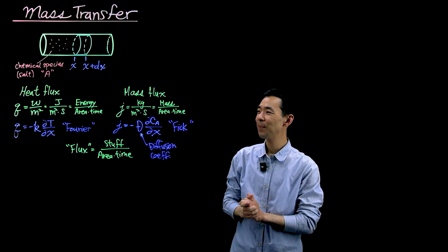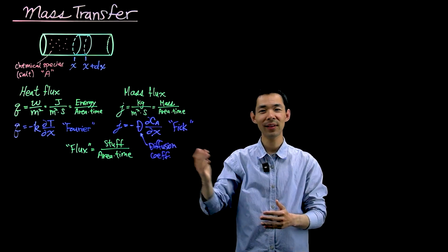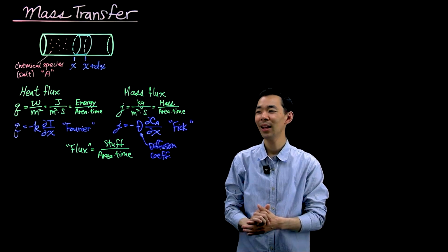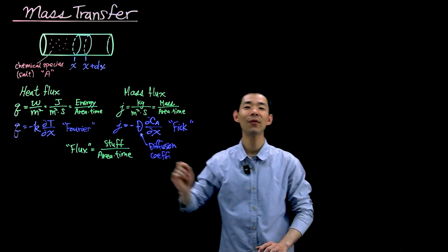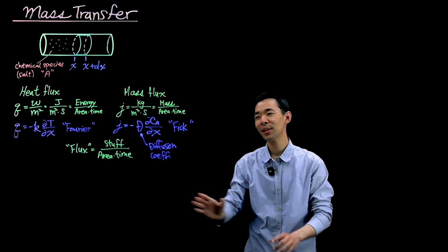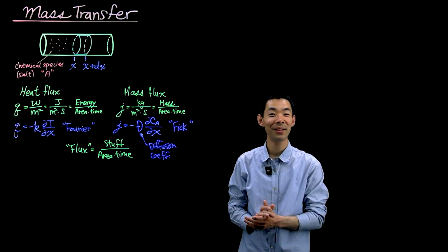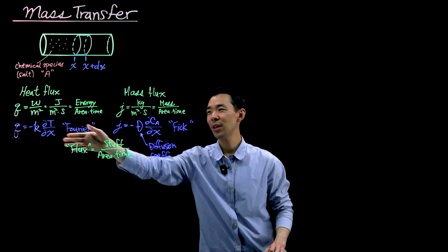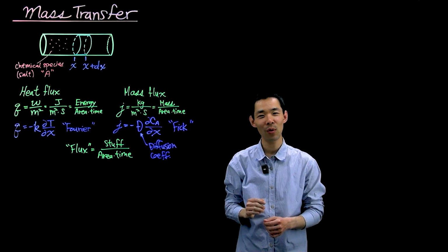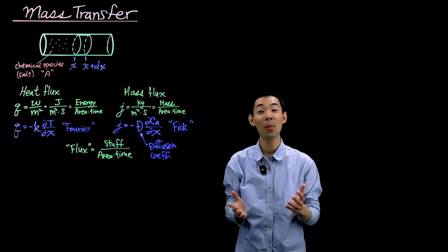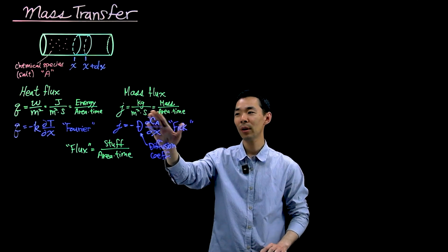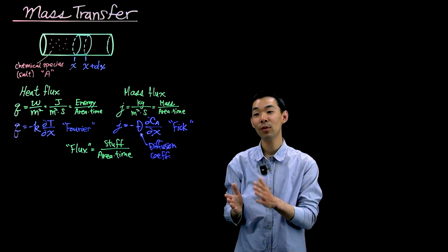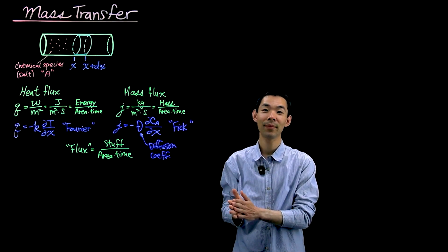So it turns out that this is called Fick's law of diffusion. Again, not really a law, Fick's constitutive relation. And it's identical to Fourier's relation. Now, there is a third relationship that is very famous for momentum balance. So we have energy, mass. The third conserved quantity that we often deal with in science and engineering is momentum. There, the variable that we're solving for is not temperature, not concentration, but instead momentum, which usually is written as the velocity field.